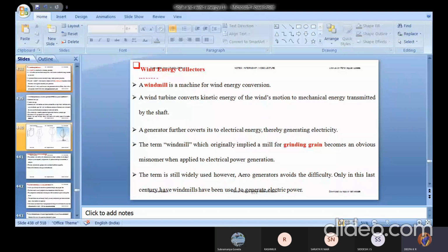Then to reduce the rotor cost, use of a low cost counterweight is recommended, which balances the long blade weight centrifugally. Cost wise, small scale cost is somewhat acceptable because 10,000 or 15,000 looks small for the installer. But if I say 1 crore, 2 crore, then they will start thinking, should I go for this installation? So to reduce the rotor cost, use of a lower cost counterweight is recommended, to reduce the weight as much as possible, because it was given as per calculation for 1 kilowatt of power.